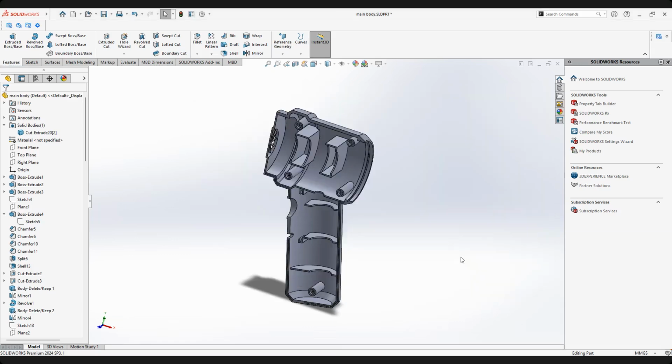Okay, it means that save as copy and continue means I have already created a new file named rear casing, with only one solid body. So I'm not disturbing this main file, hold on, I need to type this. This main file, as you can see here, is main body. We still have the original backup main body where we have front and rear casing, but I already created, with save as copy and continue, a file named rear casing that has only one solid body, right?